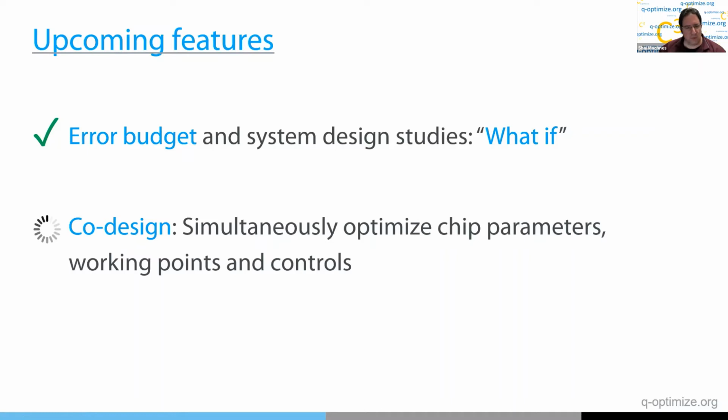For example, if you don't penalize higher anharmonicity with greater noise due to charge sensitivity, the optimization will immediately go to extremely high anharmonicity. You have a true two-level system, but that's not realistic. So everything has to have a price. We need quite a robust model that exacts a price for every change in parameters.